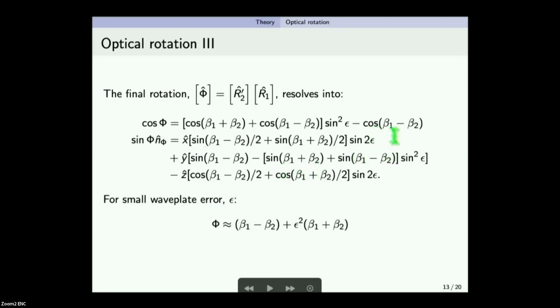If you delete the error, you can see that it all reduces down to this Y term here, which is just the subtraction that you would expect from two subtracting signals. But if you do include the error, you have this extra small term that adds the signals together, that scales proportional to this. And this is sort of our upper limit, or our limit on how well we can actually do the subtraction from the intrinsic radiometer.